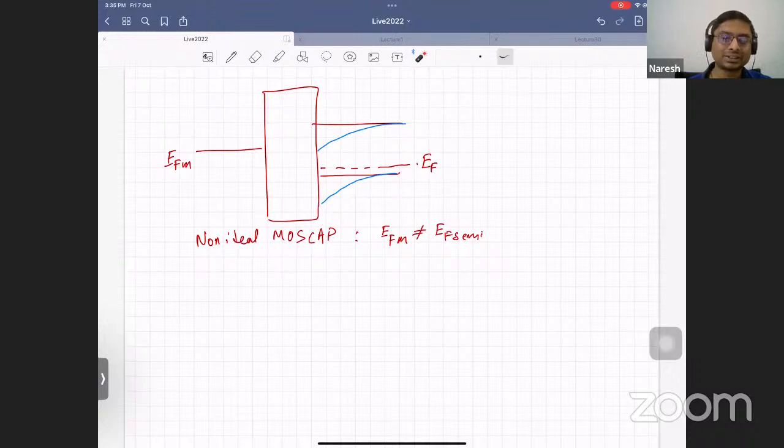In fact, the technology names, 250 nanometers, 180 nanometers, came not from the MOSFET, but from DRAM technology, wherein the half pitch, the distance between two DRAM cells in the memory, quantified how good the technology is. So people started using that number. But anyway, now it has no physical meaning, except that we are still paying homage to Gordon Moore and his law.